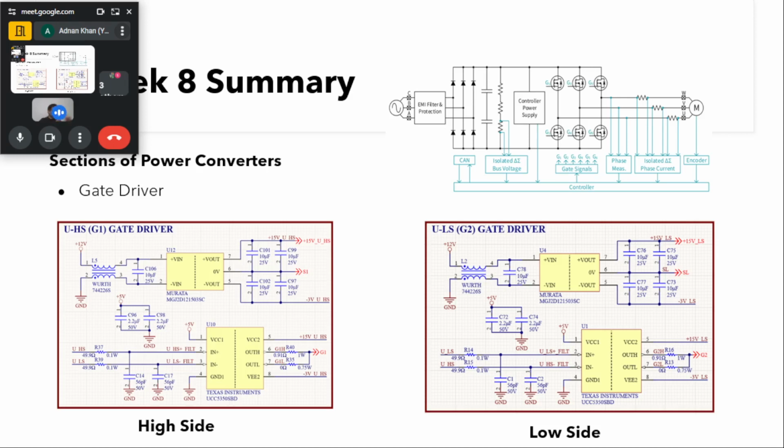What we saw is that the low side devices usually have a common source potential that does not fluctuate. It is at a constant potential, and you can see here the sources of these bottom devices are at the constant potential of minus VDC. But the source potential of the high side switches usually fluctuates between 0 and VDC.